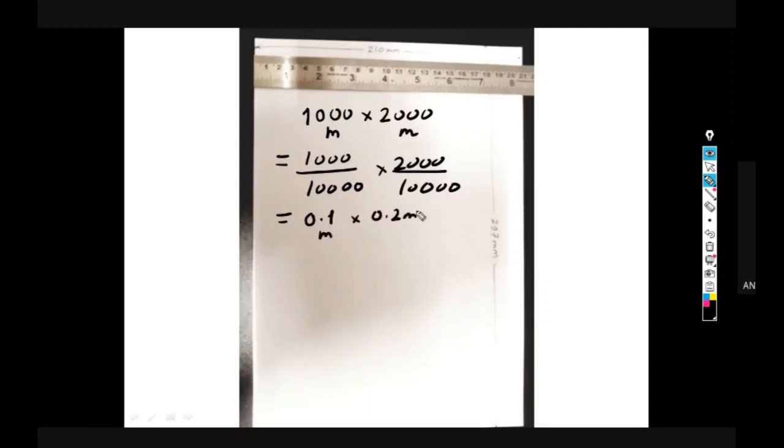So on paper generally we use millimeters. So how much is 0.1 meter on the paper? 100 mm, yes, right? And what is the width of the paper? 210 mm. So definitely 100 mm is possible. So your scale of 1:10,000 is a good choice. You can draw it by 10,000, right? Are you getting what I'm trying to say? How to understand the scales? Yes, sir. It's very easy.